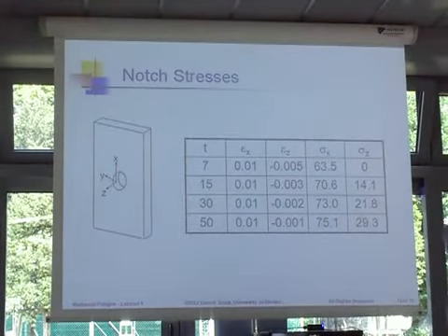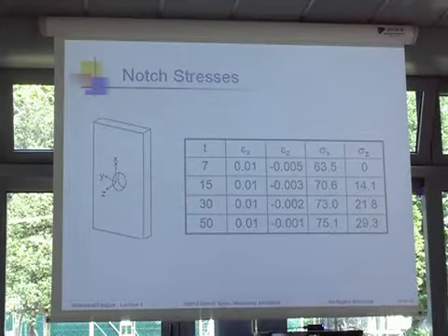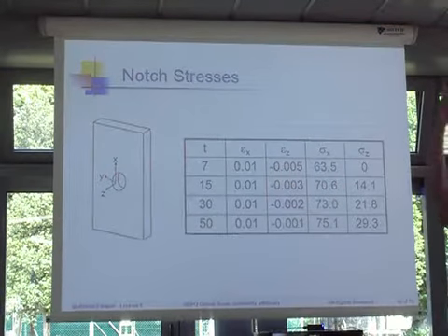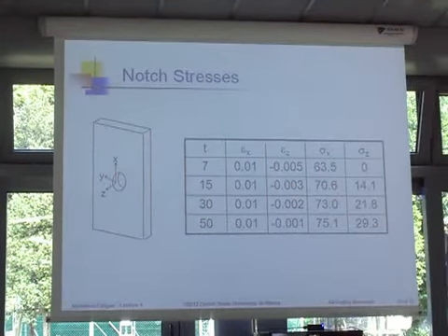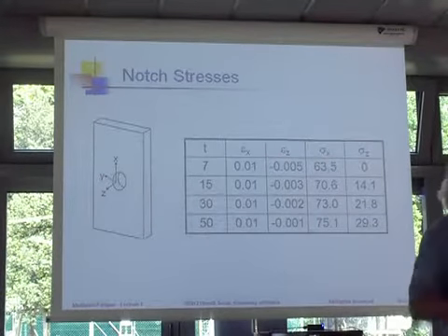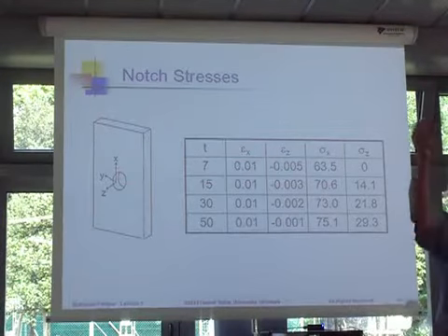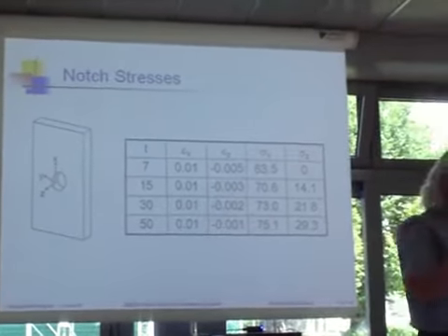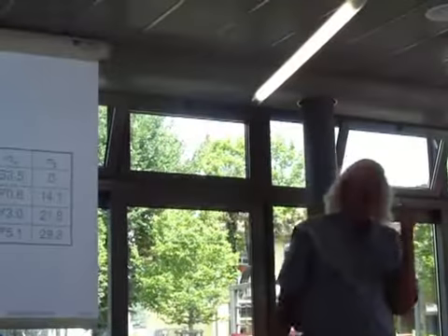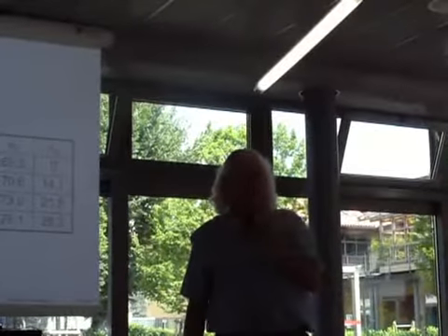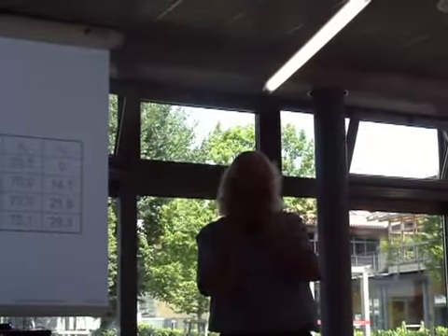Because the thicker plate prevents the transverse contraction, it's in a state of plane strain, and so the stresses will be higher by about 1/4. And you find in the test, the thicker plates always fail first. In the thicker plates, the cracks always start in the middle, where the stresses are the highest. So this is a multiaxial fatigue problem, even though the geometry is very, very simple. So the only true uniaxial fatigue problems come for situations of very thin structures in plane stress.